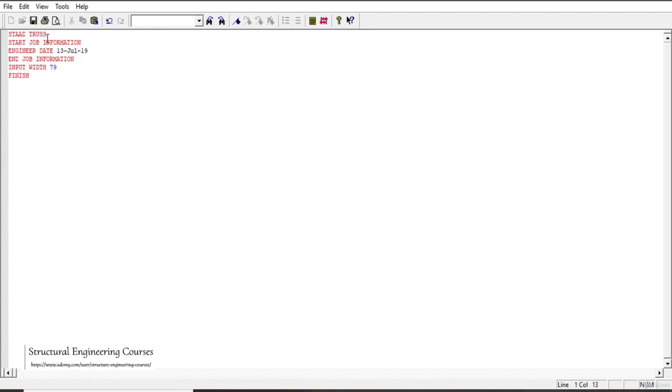So instead of space, if you enter the truss, then STAAD will specifically know that there shall be no out of plane forces. So that is also a very important concept that you do need to understand. Sometimes it does happen that we go for STAAD space, that is also not specifically wrong, but what happens is that out of plane forces also come into picture in that case. So to avoid that and to make the truss much more economical also, we use the STAAD truss options.